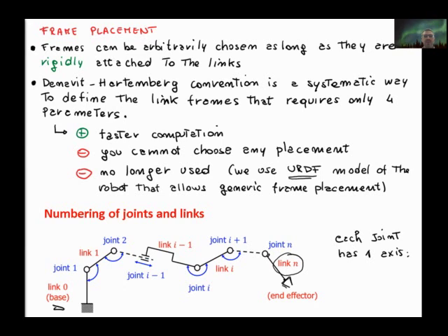And we said we are not considering spherical joints or 2 degrees of freedom joints, so each joint has one axis, and they can be either revolute or prismatic. This is an example of prismatic, and these ones are all revolute. And they have these signs to recognize them.